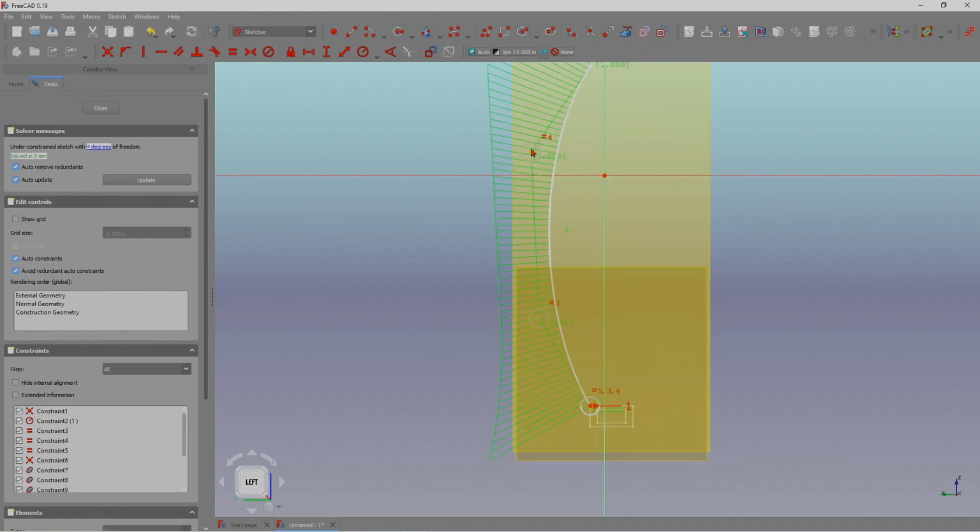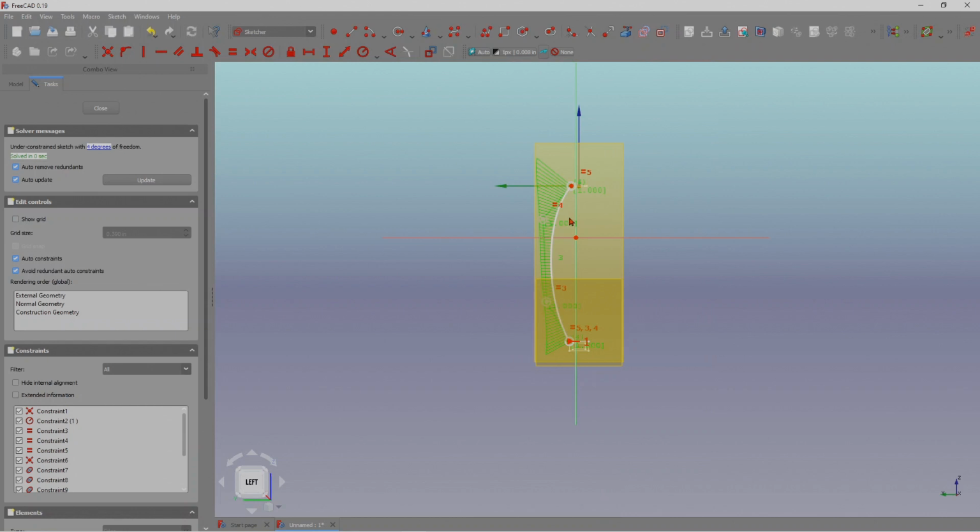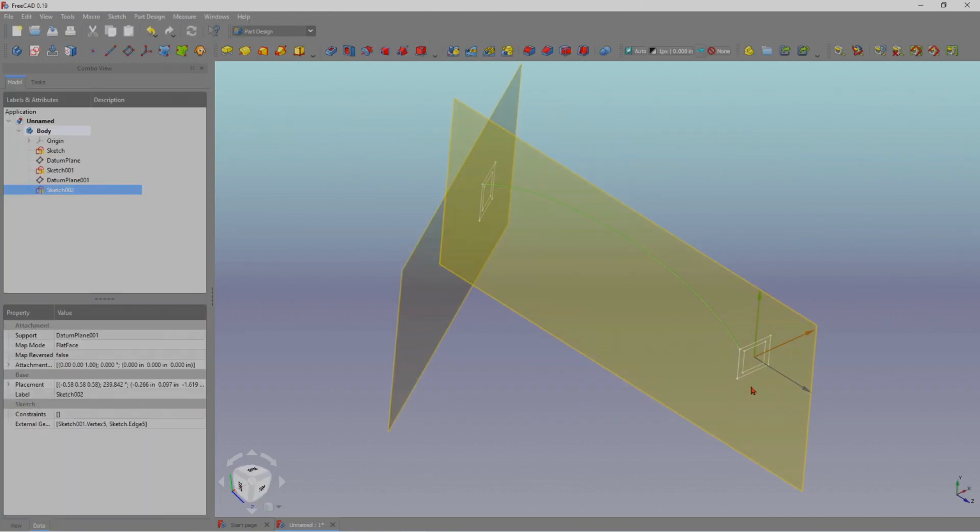Once again, this sketch can be constrained. It could have definite dimensions to it, all kinds of stuff, but I'm not going to bother. So I'm not going to constrain it. I'm going to get out of it. So now you have 2 rectangles connected with the B-spline. Since we came this far, let's finish it up with the sweep option.